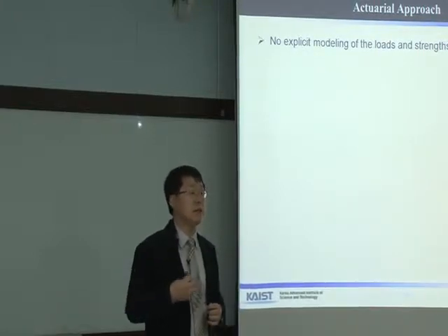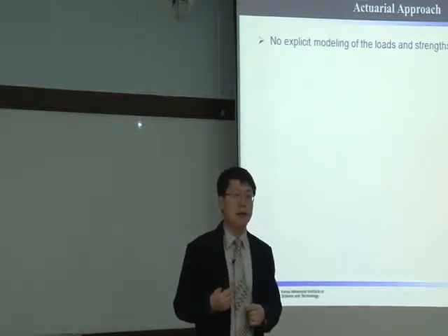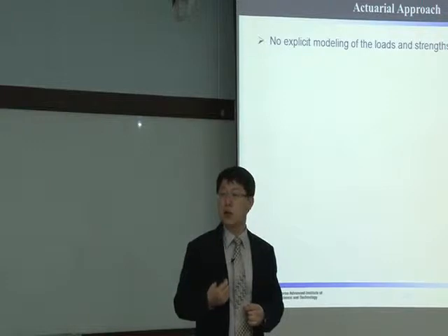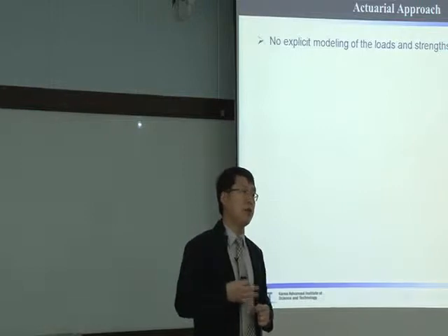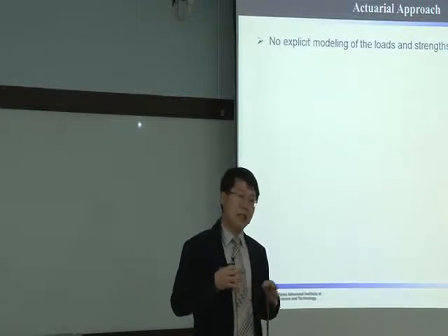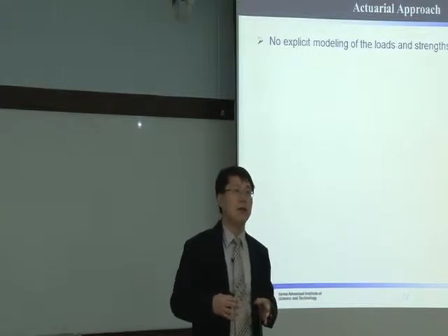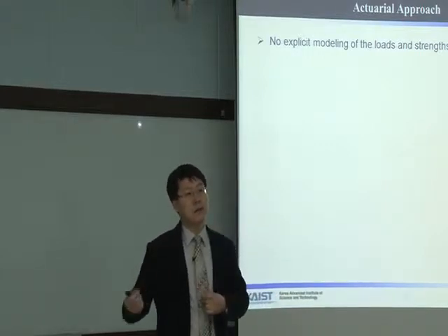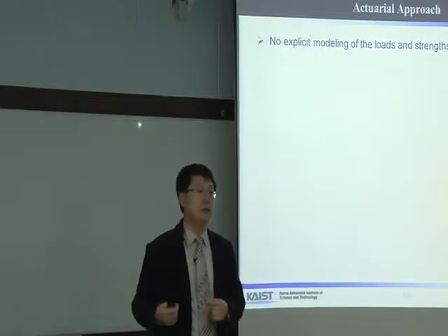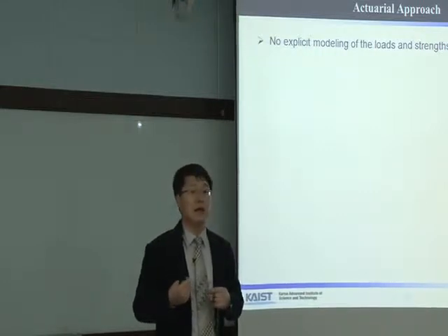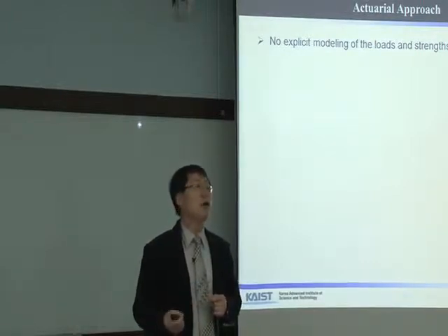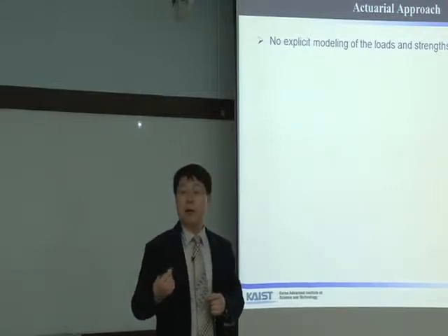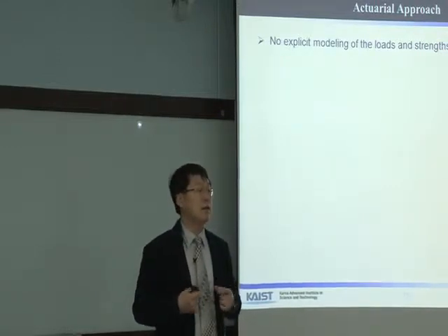But structural reliability itself cannot answer the question: what is the external load? What is the design load? For example, in the offshore industry, the design load of the structure comes from the process, fire and explosion load. So the structural engineer cannot find their load from fire and explosion. It should be supplied by the safety engineer who has some experience in process and safety.